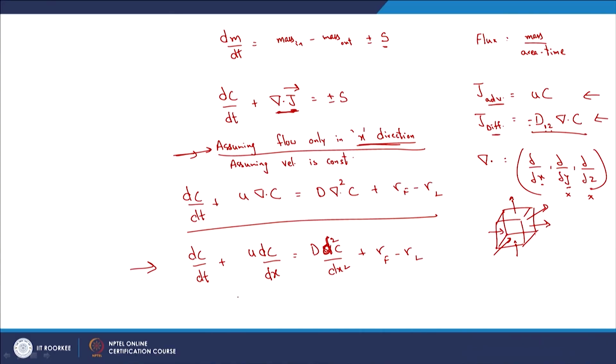So, if I am trying to apply it to the compound being transported from Haridwar to Roorkee, how will this equation further transform? So, dC by dt plus u dC by dx. I can neglect the diffusion term, because whenever I have advection, typically diffusion is relatively negligible, right. But that will not be the case obviously in groundwater, because the velocity of the flow of that particular fluid is pretty less. But in surface waters, the velocity of flow of that fluid is relatively high, right. Thus, you can neglect diffusion, but not in the case of groundwater though.